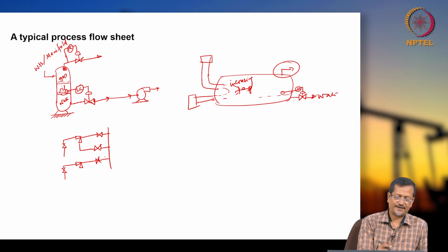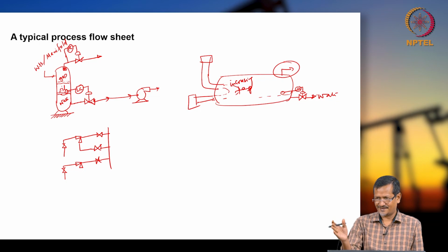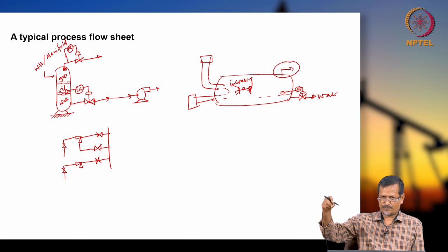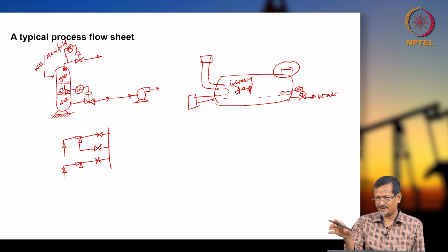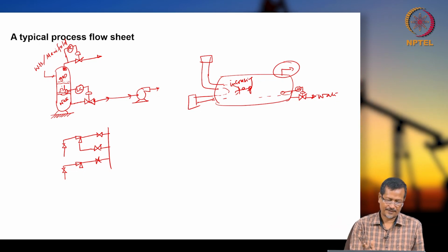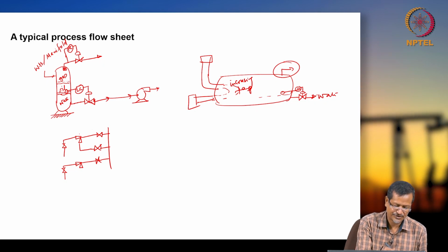You cannot keep anything uncontrolled. If there is any leakage somewhere, you must be cutting off that area, so you must have a nearby valve. Because of one leakage, one problem, you cannot shut down the whole thing. Maybe you will be stopping that small area and replacing that pipe or tubing, or rectifying the system. So you will have many valves and flow systems. So these are manifolds actually, production wellhead.